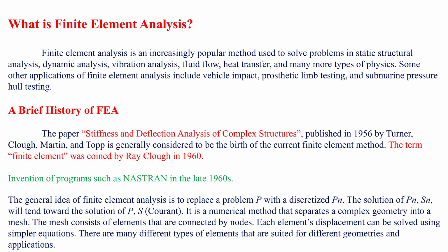Generally, finite element analysis is to replace the problem P with a discretization, that is Pn. If we consider the solution Sn of this Pn, it will tend towards the solution S of P. Okay, so it's a numerical method which separates the complex geometry into a mesh.